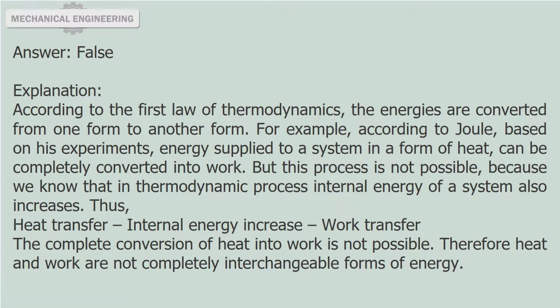Answer: false. Explanation: according to the first law of thermodynamics, energies are converted from one form to another. For example, according to Joule, based on his experiments, energy supplied to a system in the form of heat can be completely converted into work. But this process is not possible, because we know that in a thermodynamic process the internal energy of a system also increases. Thus, heat transfer = internal energy increase + work transfer, so the complete conversion of heat into work is not possible. Therefore heat and work are not completely interchangeable forms of energy.